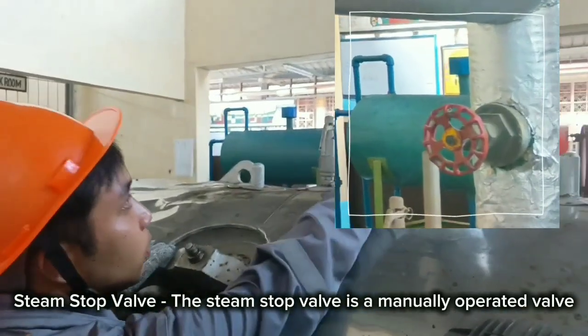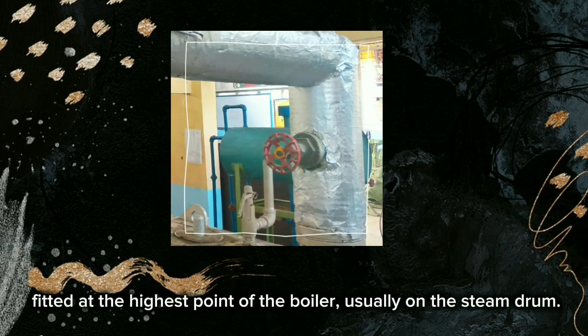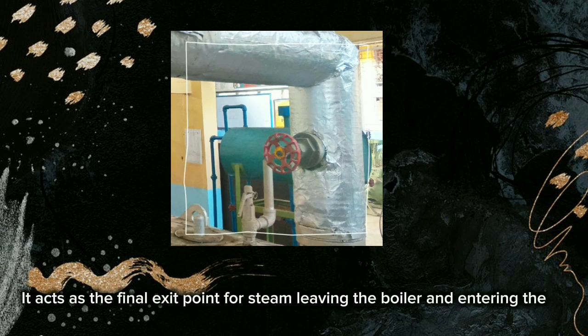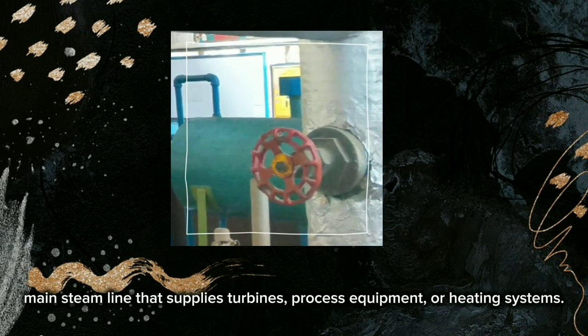Steam stop valve. The steam stop valve is a manually operated valve fitted at the highest point of the boiler, usually on the steam drum. It acts as a final exit point for the steam leaving the boiler and entering the main steam line that supplies turbines, process equipment, or heating systems.